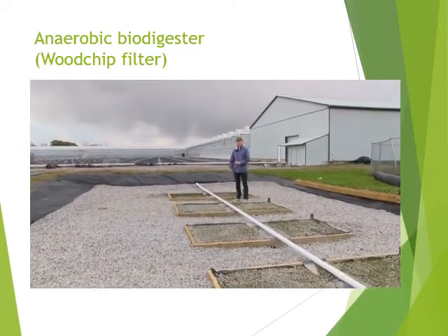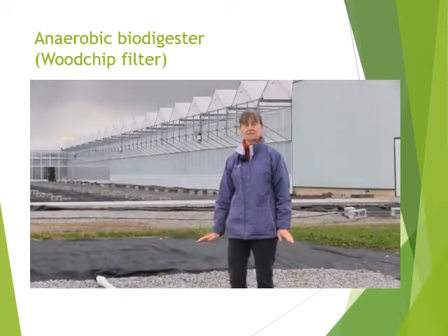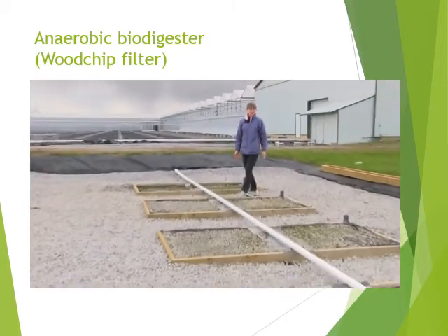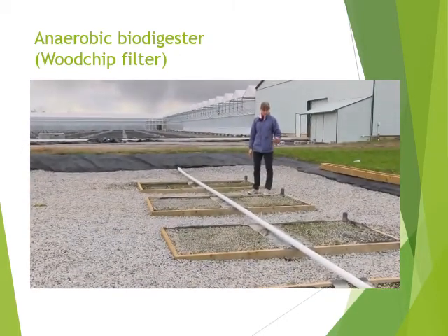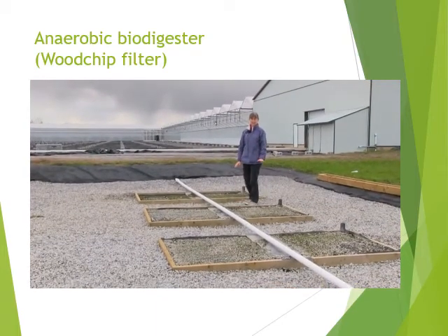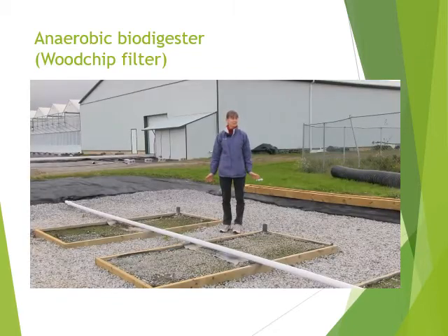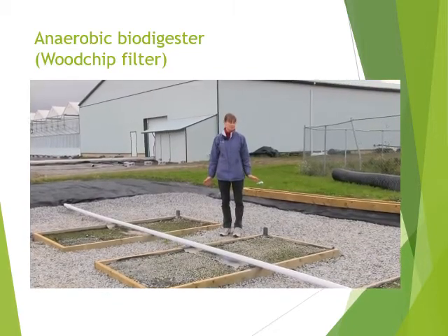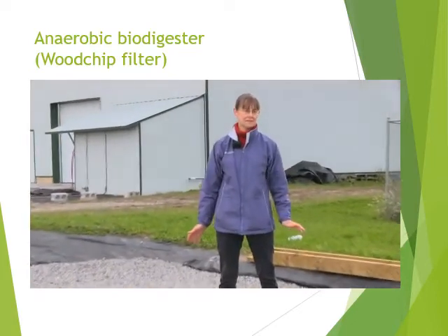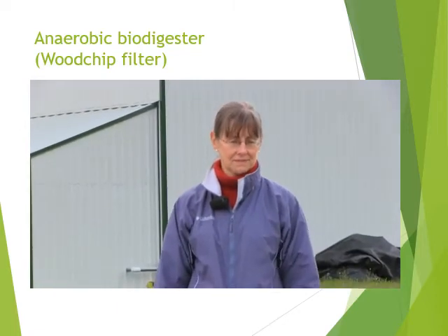Underneath a thin layer of gravel there's about 7 feet of wood chips, and this is designed to remove nitrogen. The smaller trays here are layers of slag over peat, and the slag is designed to remove phosphorus from the runoff water. This system has been operating for 5 years. Since then, we have been monitoring the effectiveness of the system to remove nitrogen and phosphorus.